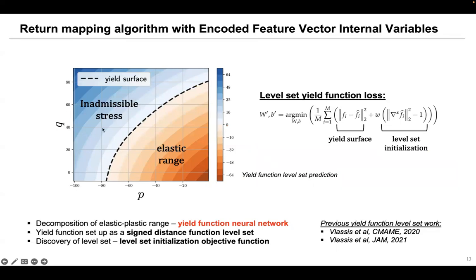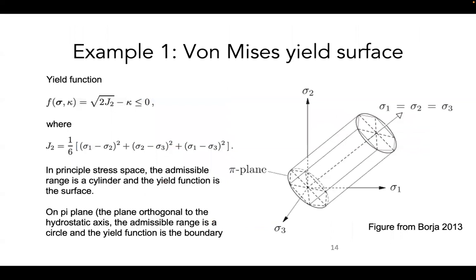So that's another major difference between elastic and plastic. If you have a linear elasticity material, and it always remains linear, you can get any stress combination. Any imaginary number, maybe 1 trillion gigapascal, you can get it. Because it's linear, you have a mapping, you can just have some very big stress. For a plasticity model, there is only a range of stress you can achieve, taking into account the hardening, because ultimately the material may fail. And that combination is determined by the plasticity model.